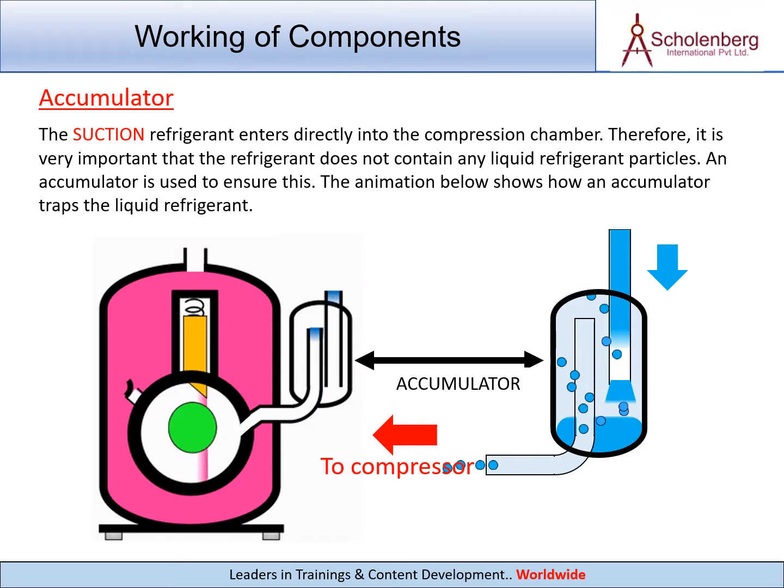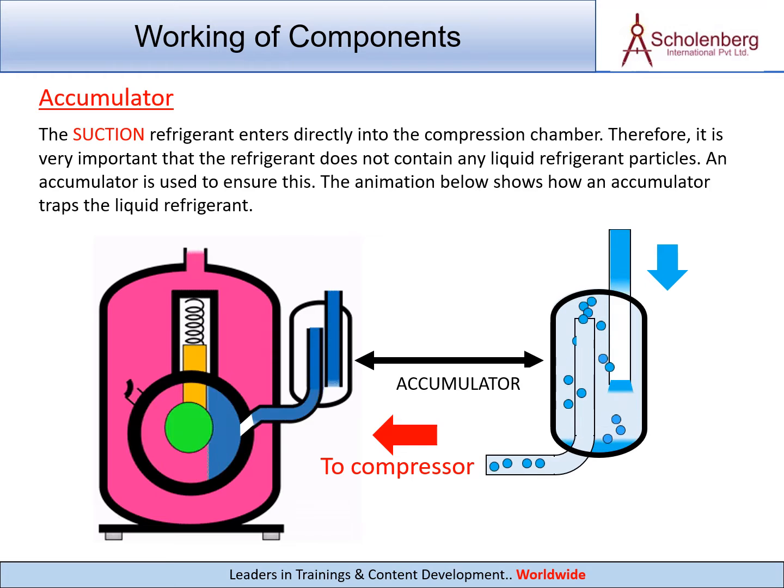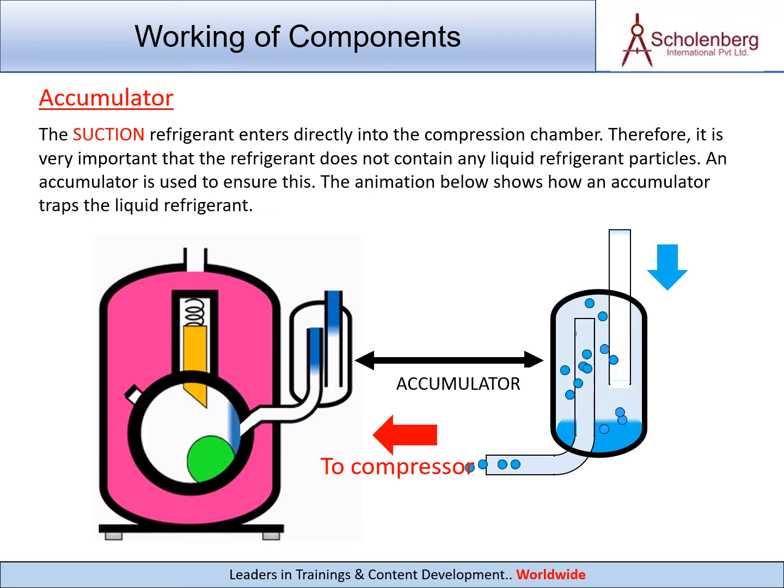Accumulator. The suction refrigerant enters directly into the compression chamber. Therefore, it is very important that the refrigerant does not contain any liquid refrigerant particles. An accumulator is used to ensure this. The animation below shows how an accumulator traps the liquid refrigerant.